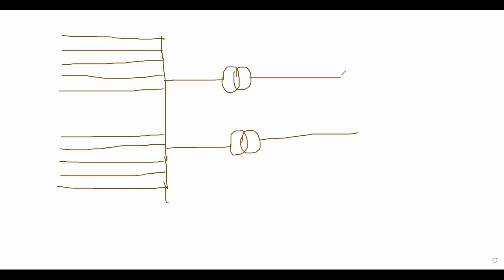And these 5 feeders are connecting to this. Fine. And again, these two are connecting to a bus. And again, 2 lines, supposing again the reliability on the lines. Generally, always 2 lines will go out from your substation unless the utility is not allowing you. Mostly 2 lines will be there. If one of the lines fails, the other will be there. So this is the skeleton view of your project.